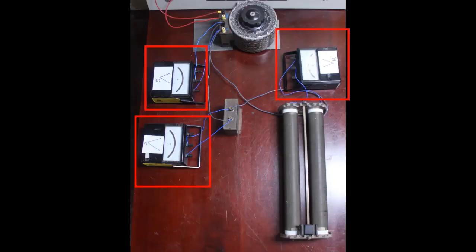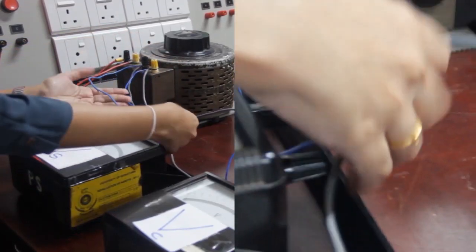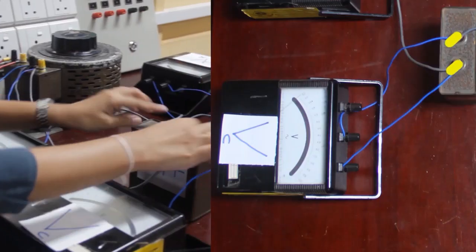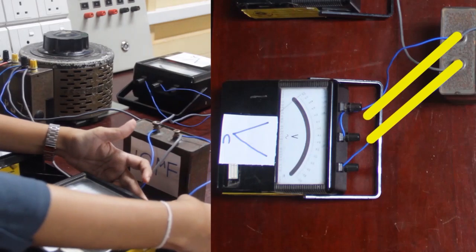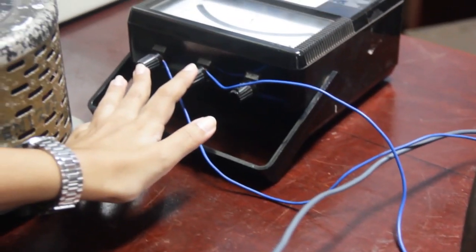We are connecting all the voltmeters in parallel to the apparatus to measure the relevant voltages. When we are connecting voltmeters, depending on the measurement, we can select the range we need. Here we have 0 to 150 volts and 0 to 300 volts range. For this practical we are selecting 0 to 150 volts range. We are connecting Vs voltmeter in parallel to the voltage source in order to measure the source voltage. To measure the voltage across the capacitor, we are connecting Vc voltmeter in parallel to the capacitor. Similarly, to measure the voltage across the resistor, we are connecting VR voltmeter parallel to the resistor.